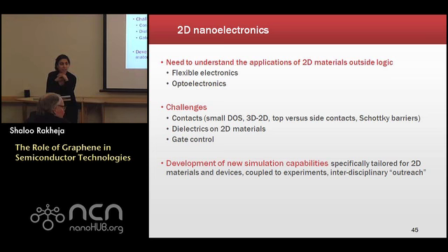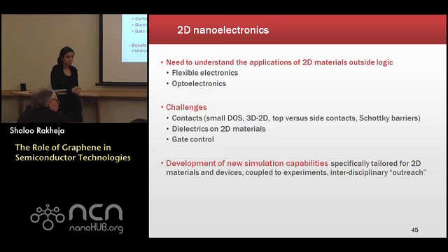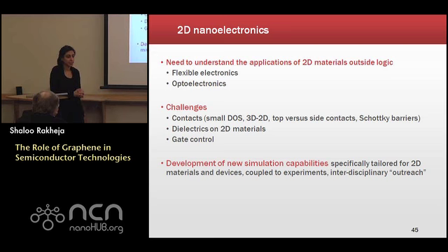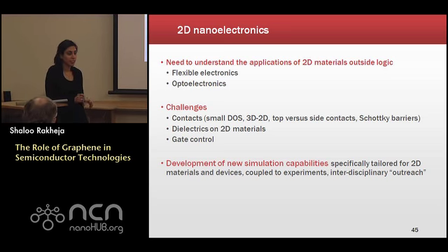So, speaking of ballistic transport, do you think that this zeta parameter that you alluded to is fairly well reproducible across a broad range of samples, or is each experimental procedure going to produce its characteristic zeta? Because you seem to be assuming that zeta was uniform across a set of devices with different channel lengths. Now, zeta actually scales with channel length. The shorter you make your channel length, zeta becomes higher, because zeta is ballisticity, and you have to compare your channel length with the mean free path for that technology.